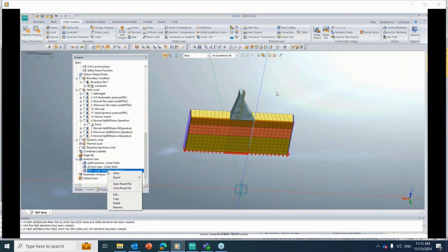Then they decided to see up to what extent the structure can be allowed to go without being totally damaged, without breaking. It can have some plastic hinges, it can go beyond elastic limits. So that reduction factor they apply to this, that is called the response reduction factor, and they come out with the seismic coefficient for that, and that force they applied.